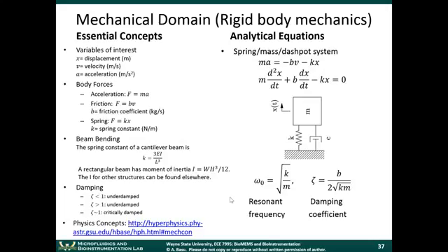So the goal would be to have an underdamped system? Good question. So the question is, is the goal to have an underdamped system? If you want the system to recover from whatever perturbation you gave it, the system that returns to its initial state the quickest would be the critically damped system. The overdamped system resists.